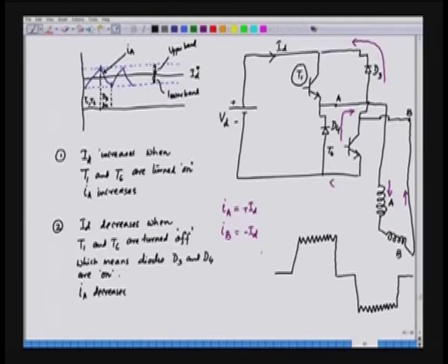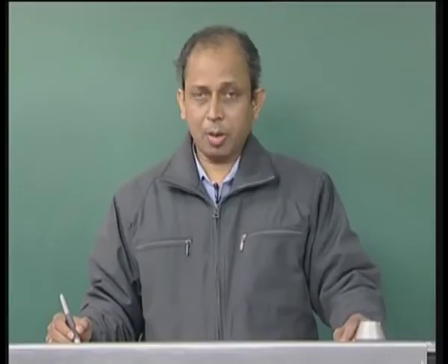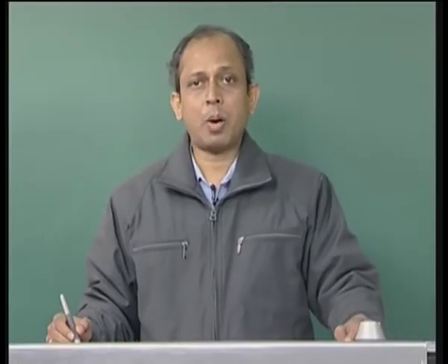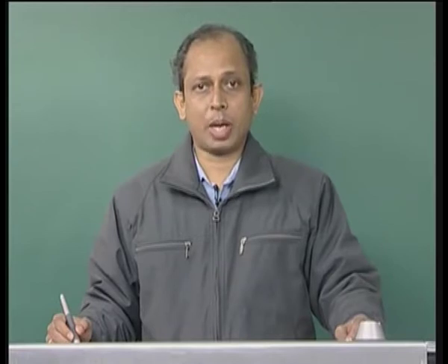So, this is the nature of IA, which can be approximated to approximately quasi rectangular waveform like this. Although we have the reference current which is a quasi rectangular, the actual current follows the reference within a hysteresis band. Now, let us try to find out the power in a brushless DC motor drive.